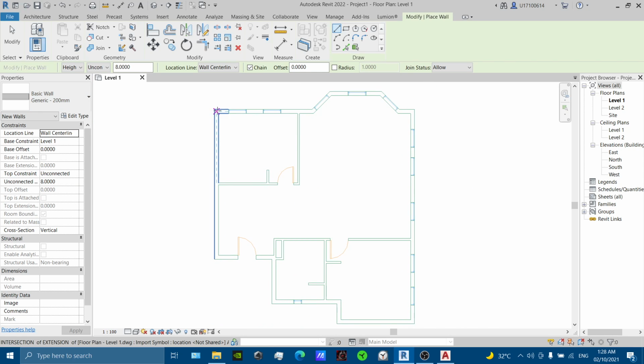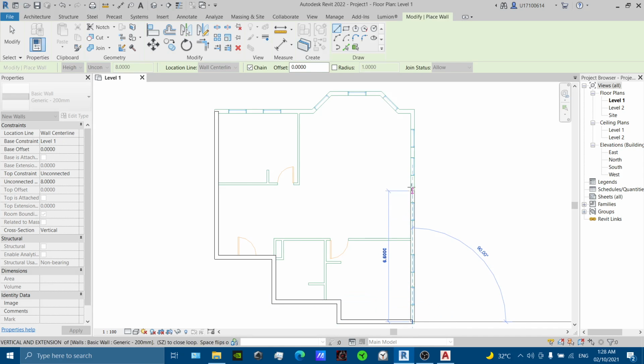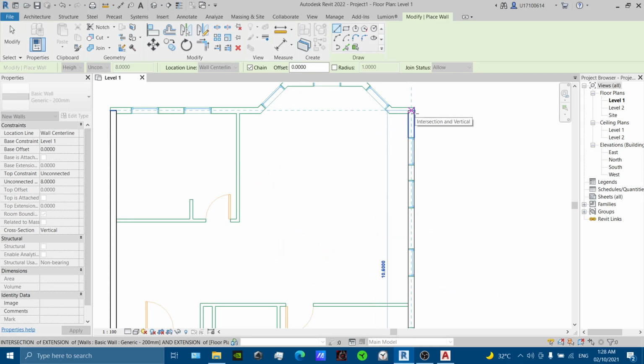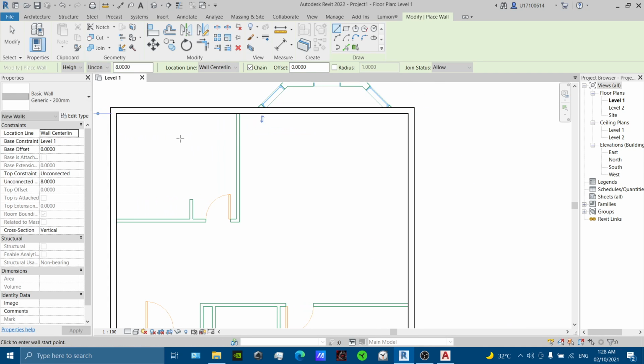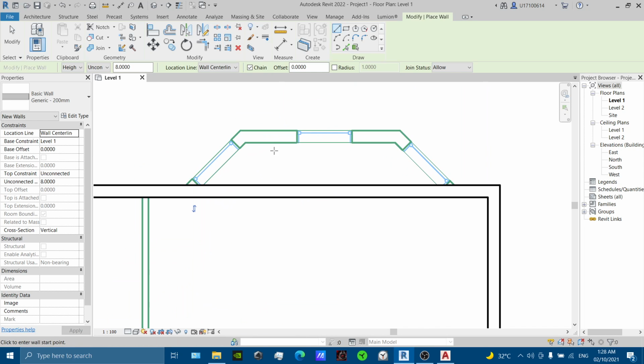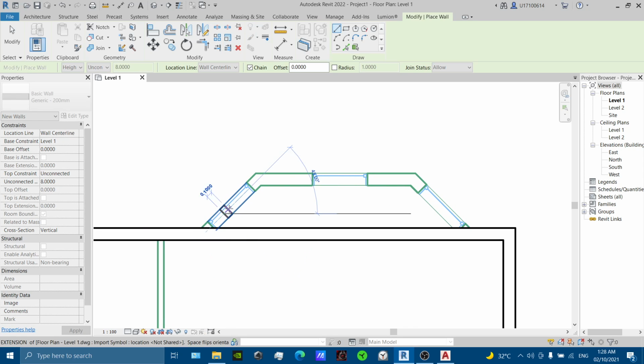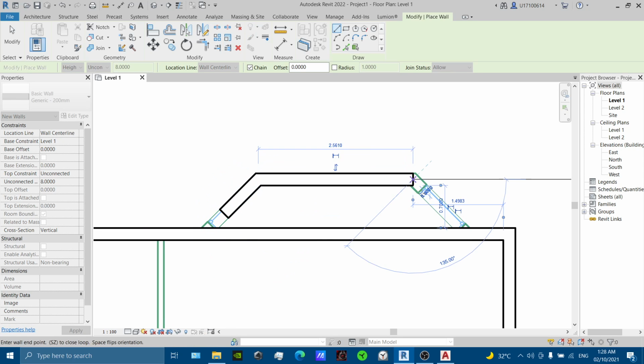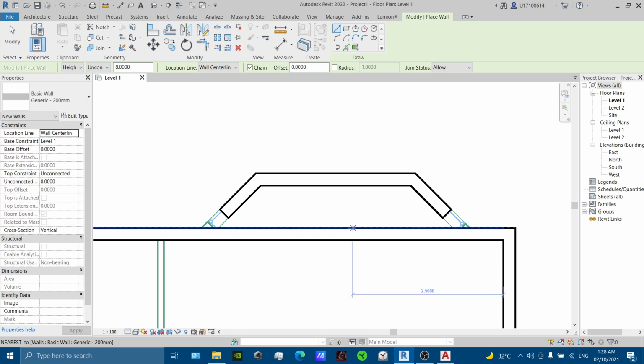So once we see the crosshair here for our cursor, we can start designing or placing the wall onto the plan. So we're going to trace it even on top of the doors and on top of the windows, which I will explain later. So let's assume that we accidentally continued the wall and forgot to include this small portion of wall right here. One way to solve this issue, we can trace this part here with a wall, but it would still be disconnected from the bottom one.